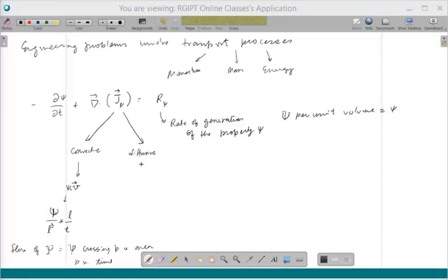And the diffusive flux, this relation we get from constitutive relationships. The convective flux has nothing to do with material property. It has all to do with the transport. If you have two different materials, as long as velocity is the same, the flux will be the same.